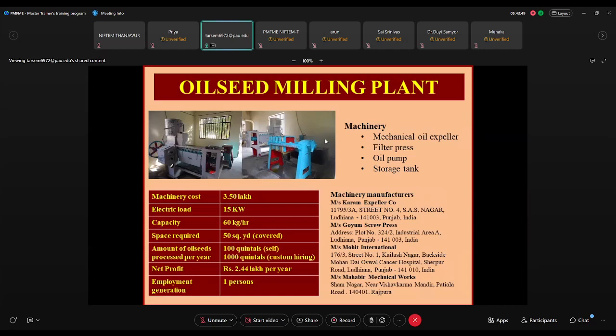Another one is removal of the free fatty acids. There are free fatty acids which are soluble in the oil but can deteriorate the quality of the oil, so they have to be removed. During refining, we remove these free fatty acids by using alkali refining or some physical method of refining. Again, this is not possible at the farmer's field.